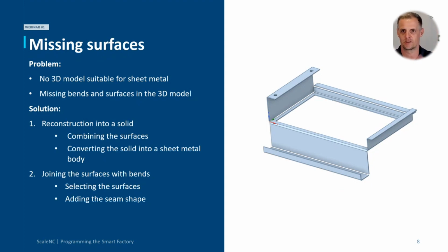Third method is collecting the inside or outside face, thickening it up to the right thickness, and after that I can convert it to a bending part or sheet metal part, and in this case creating only one solid from these 4 solids.